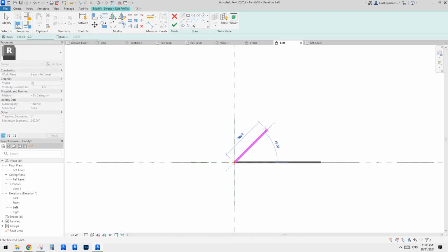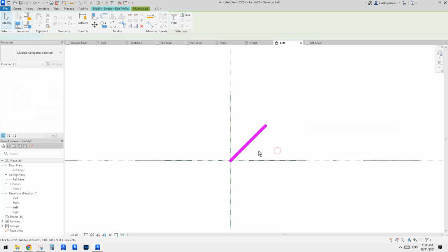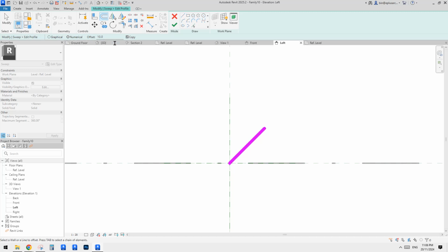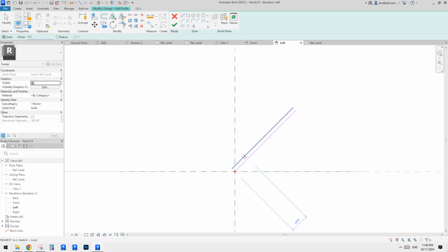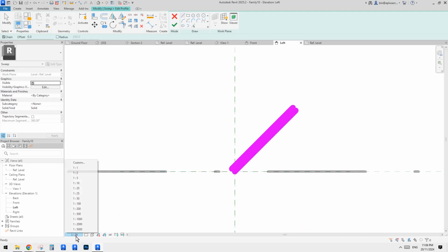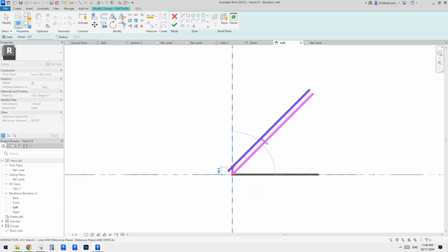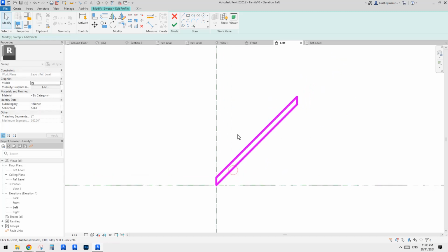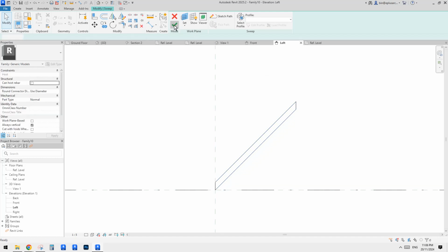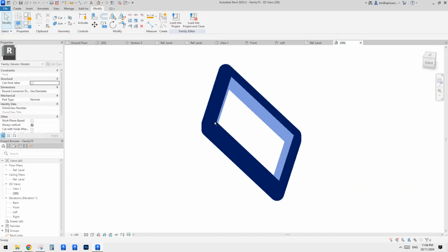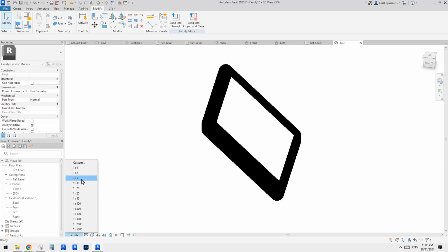Okay, I think I can probably do this. So it's same. I'll just draw 150, right? So 150, go up 150, 150, draw it back, delete, offset 10. That's fine. And line, or TL again. Maybe change your scale instead. So not too thick, not too thin, right? So trim, TR, finish. So now this is like a model. So I'll just change the scale here as well. Change it to 1:5.